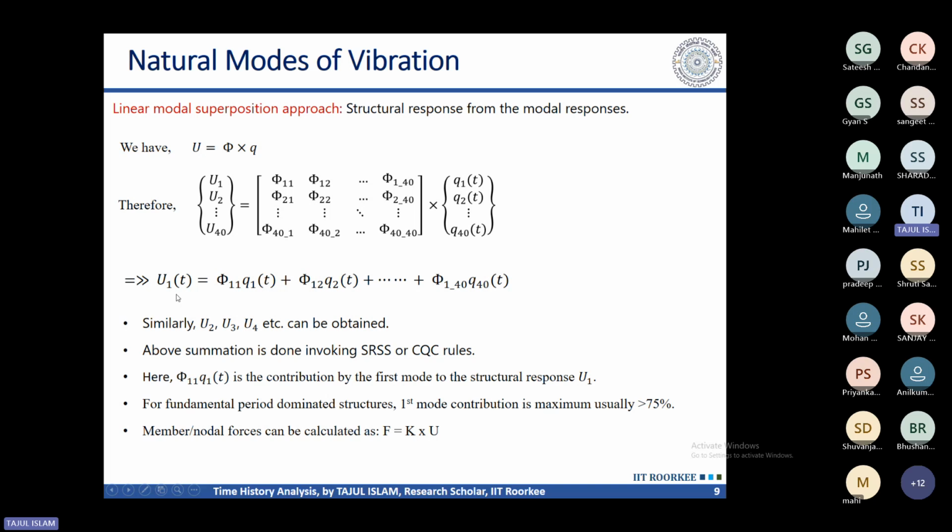So here you see the actual deformation. This is the deformation that you are going to see in your software. Let's say you have applied a lateral load of 100 kilonewton to your structure. Then when you open your output, the result that you see will be this one. This one you cannot see; you have to understand it mathematically. The software gets this by adding the mode shape deformations of all the modes in terms of matrix multiplication with the mode shapes.